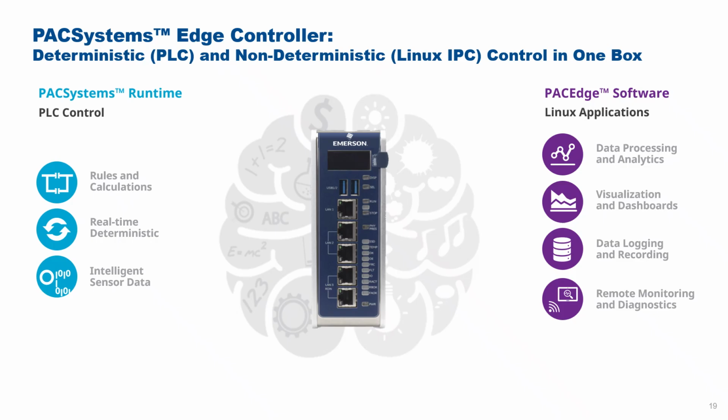With PACEdge, of course, you can also do all of the other functions that we mentioned. You've got data processing and analytics, you can do the visualization dashboards, you've got those databases for data logging and recording, and it enables that remote monitoring and diagnostics using standard tools. Instead of having to go in using Pack Machine Edition, you can make those tools useful for a less technical oriented person, and you can have it more machine focused rather than PLC focused.